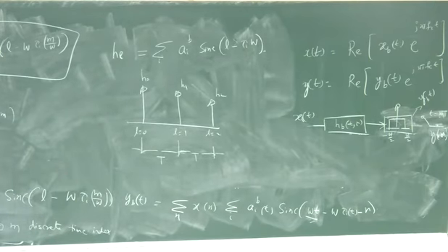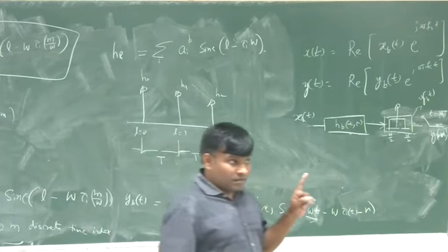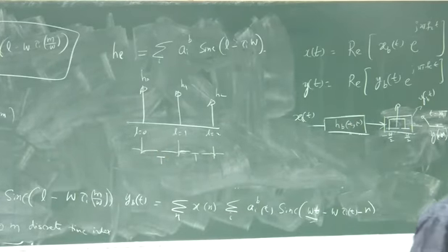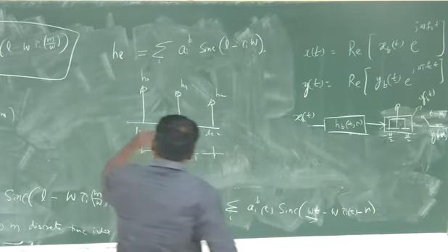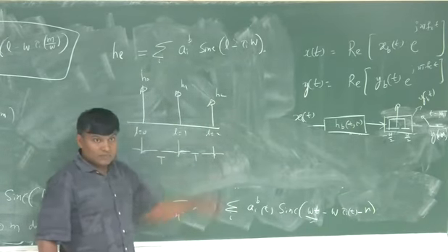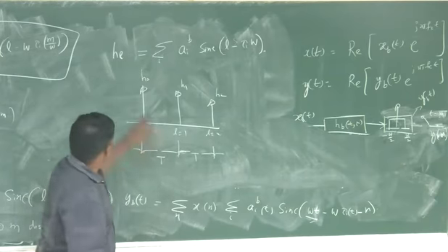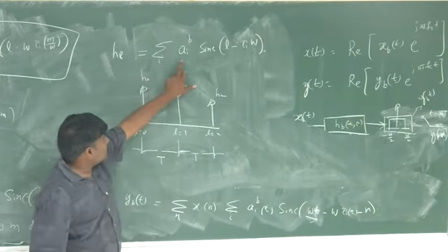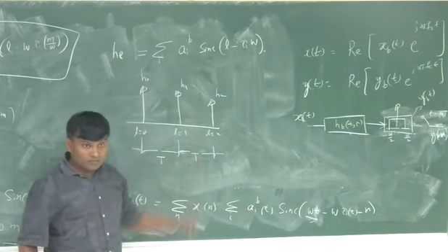Tau_i's are analog. Now everything is resolved into a T-spaced channel. The receiver is operating at T rate. Channel impulse response, so you will observe taps. What are these taps? Well, these taps are related to the original channel through this sinc interpolation.